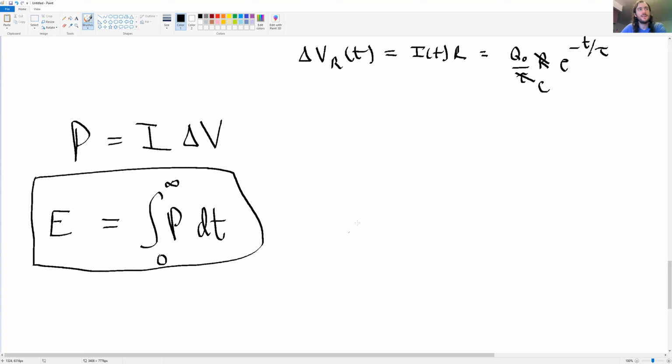So if I want to know the total amount of energy supplied by the capacitor, for example, in the discharging case, well, the maximum amount of energy stored in a capacitor is going to be 1/2 Q squared over C, right? And so if I were to integrate, and you guys check this for yourself, the energy dissipated by the resistor, check that the value, sorry, it should be Q0 squared over here. So this is some constant, right?